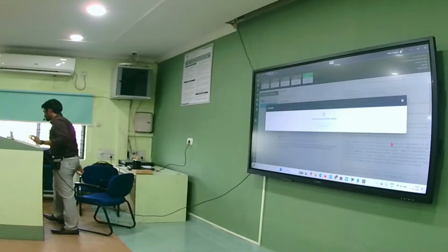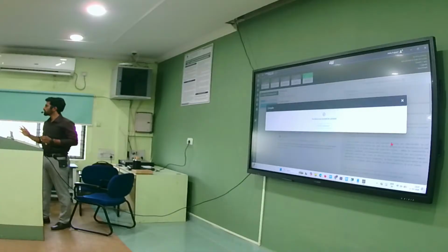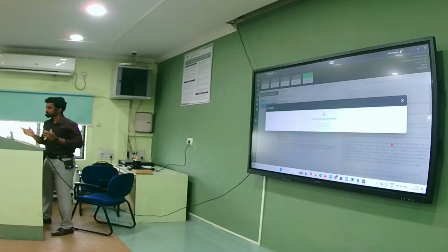Here, see, it's not showing normal, abnormal again. Normal and abnormal are detected by similarity score. For normal, it is showing 100% similarity score. For abnormal, reduced similarity score. So you can keep a threshold in your deployment code. If it is less than 90, less than 80, it should show abnormal, my red LED should glow. If it's normal, above 90, green LED should glow. Like that you can do it, based on the similarity score, you will get the output. Okay? Then close Android Studio, close everything, come back.